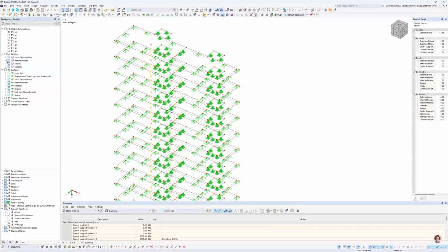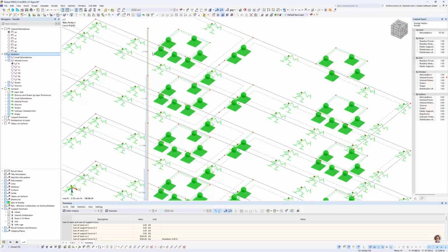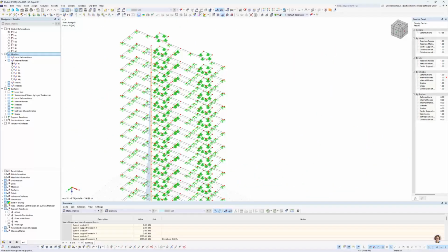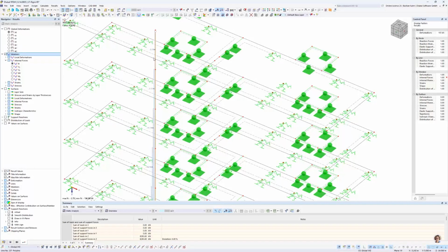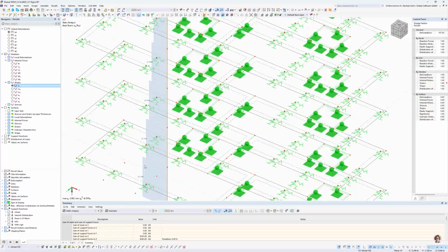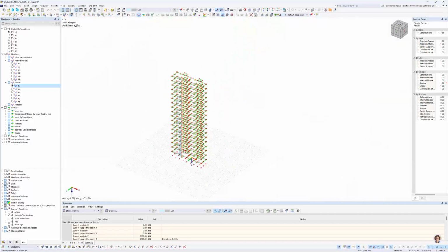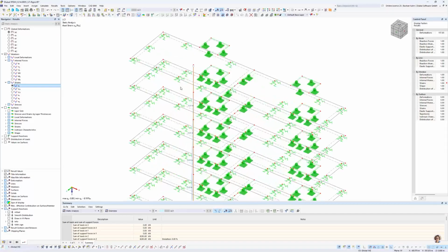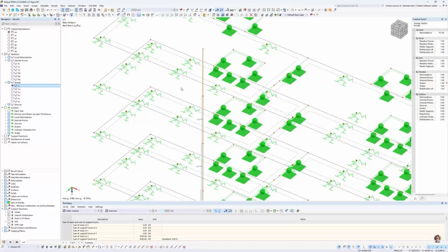I want to take a look at the internal force and the normal force, and you see, okay, that's the same structure. It has the same loading, but it only has a normal force of 3. And why is this effect occurring here? Because it's all calculated in one sudden step. And there you see the strain here is way too low, and that's why this is a completely wrong result.